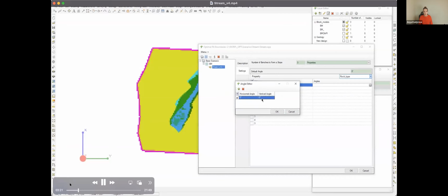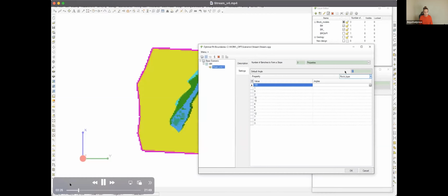And there are 3 methods that are available to set the angles of slope. The first one is to set them by area. The second method is by vector, and the third one by properties. All these methods are based on the azimuthal approach, and the vector method appears to be the most fundamental, as you can set different pit wall slope angles for directions, and overall all methods of slope angles are based on this method. The by property method uses data from the block model. So you need to specify the material class attribute, default angle, and select the required rocks from the provided list.